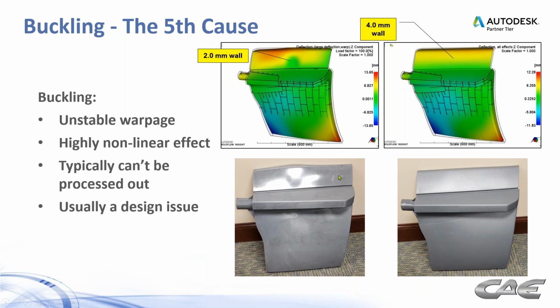In this case, they didn't really want to thicken this wall up, right? More material, etc. But after running several design iterations with different ribbing patterns on the back and so forth, that buckling pattern remained. So we ended up just sneaking up on this and kept increasing the wall stock until we could comfortably say that it was no longer going to buckle. So they implemented this 4mm wall. It was steel safe, right? They were able to add material by subtracting steel, and were able to get it out of that buckling mode. So big success there on that one.